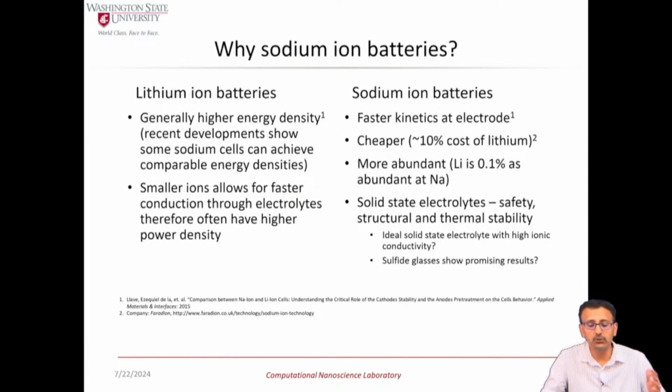So once again, why sodium, why not lithium? Besides the fact that the main driver obviously is that sodium is earth abundant, and therefore that would drive down the cost for these batteries quite a bit. So that is a huge driver in promoting this technology, but also some of the initial modeling and theory based results show faster kinetics for these sodium ion batteries at the electrode and less propensity for what is one of the major challenges in these technologies, dendritic growth. But it's still in the early stages. We don't have a full understanding of the dendritic growth process with sodium based batteries.